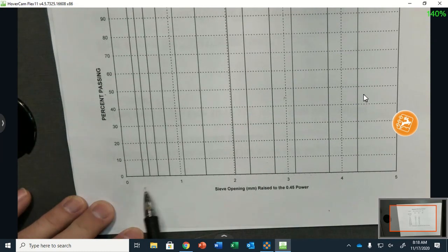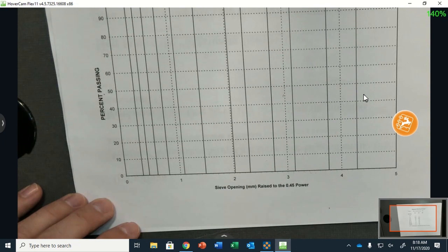So far I've taught you that the grain size gets smaller as I go to the right. Now you notice this is backwards. The sieve size is going to the left. The asphalt world likes to go to the left. In soil mechanics in my textbook that you use next year, the same gradation, they go to the left. So it doesn't matter as long as you label it.